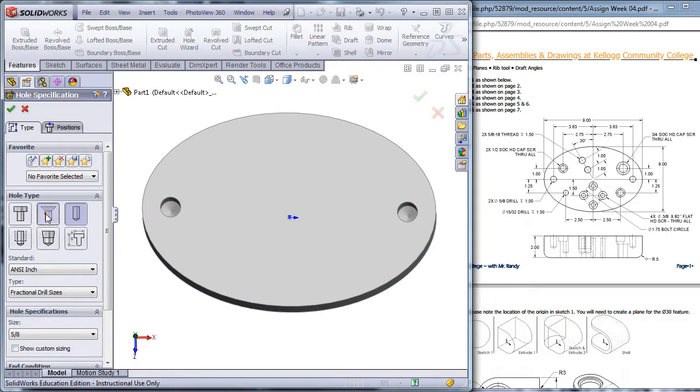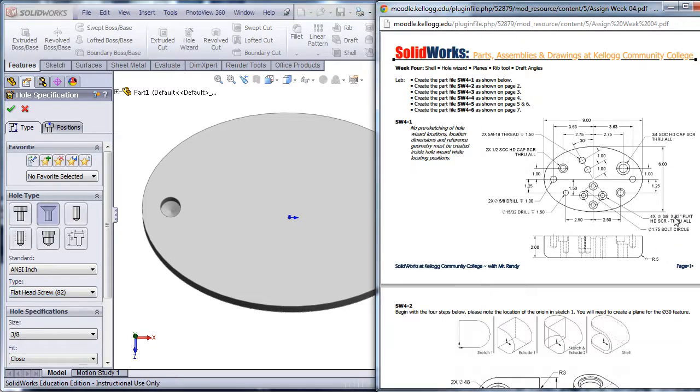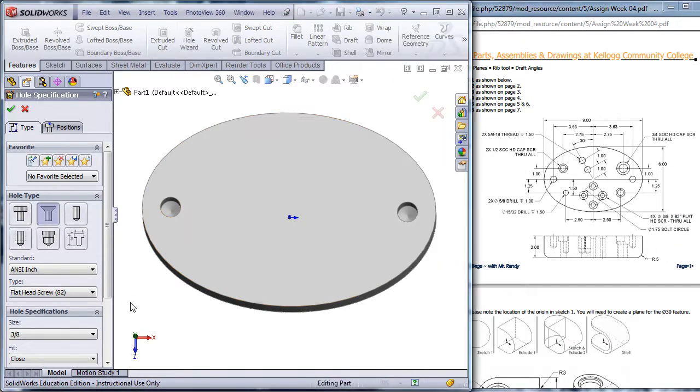And we're going to do a countersunk. For inch drawings, you can assume 82 degrees unless I tell you it's 100 degrees. Kind of standard inch screws are 82. So if you see 100 degrees, and you can see it right here in the handout, it says 82, but it won't always say that. If it doesn't say, pick 82, but I probably wouldn't knock you either way on that one.